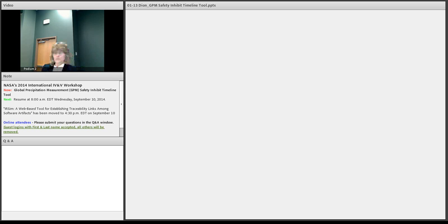And I mentioned that just like I have inhibits shown here in green, there's also a redundant set shown in the redundant boxes as well. So GPM was a fully cross-strapped system. Okay, so here's a summary of what we just talked about. So H-gas, high gain antenna, has 3 LRMs, 3 deployable hinges. Electrically, they are by design 2 fault tolerant. We had those 3 green circles, you remember. And then these are all the inhibits I can count, okay?